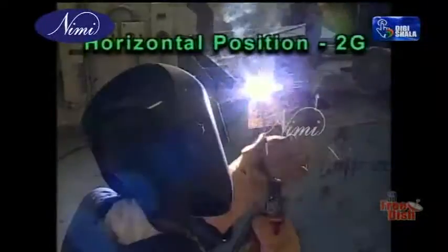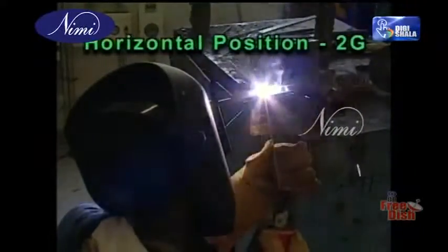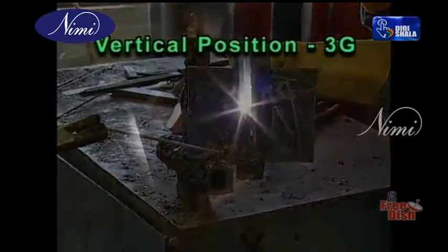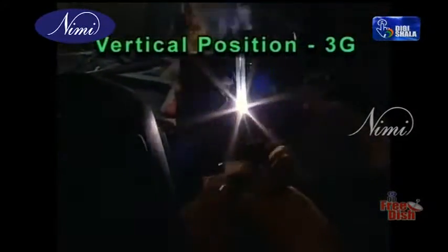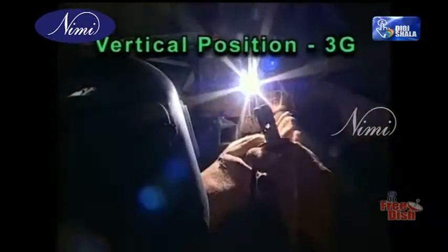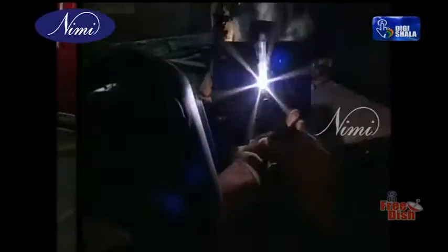Horizontal position. In horizontal position, the welding object is placed in the plane parallel to the welder and welding is carried on the x-axis from left to right or vice versa. Vertical position. In vertical position, the welding object is placed in the plane parallel to the welder and welding is done in the y-axis, that is, from bottom to top.